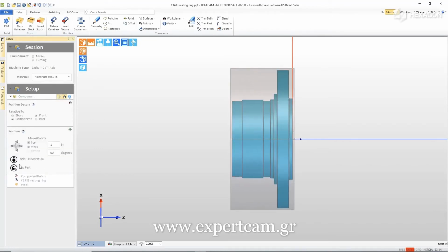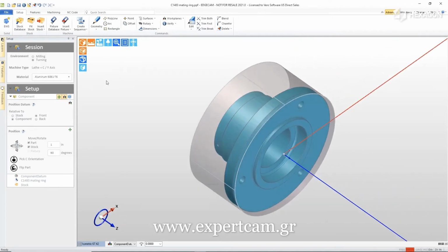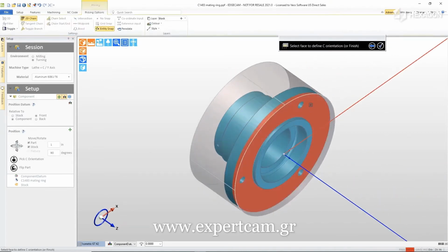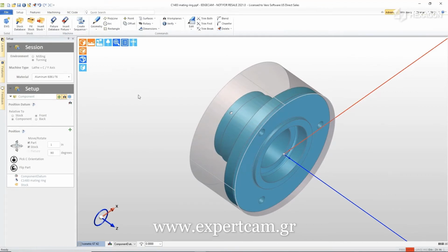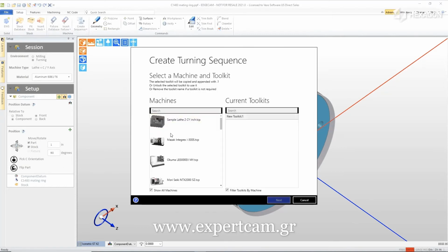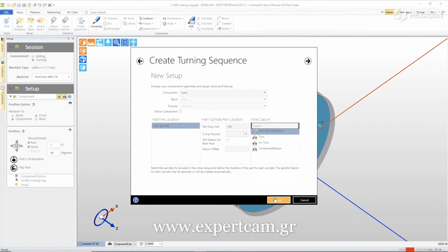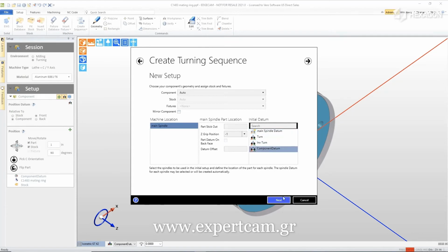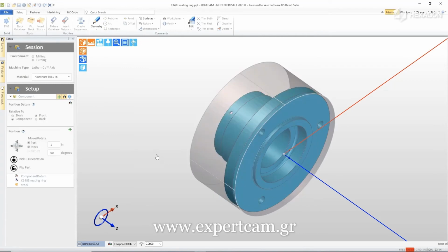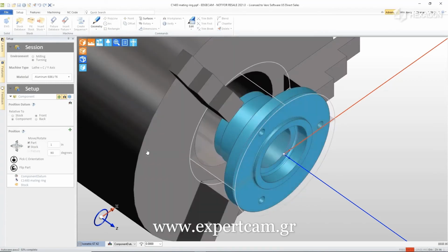And then we can also choose a hole feature in this case to clock up to C0. Next, we'll pair this to the intended CNC machine to complete the virtual CAM setup. Let's have the machine grip the part an inch behind the datum. And with that minor amount of effort, we now see visual confirmation of our CAM setup.